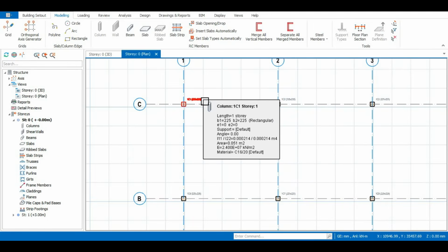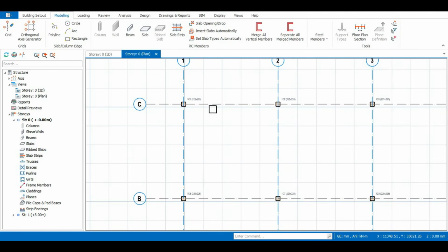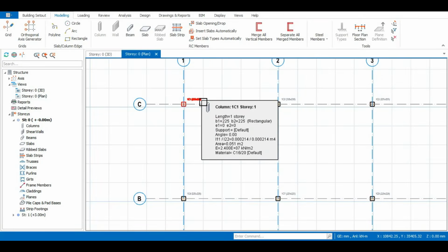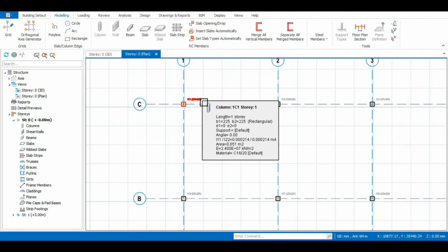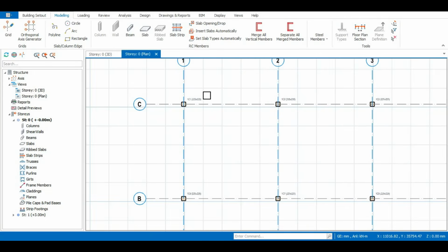And in this climate in Nigeria and most places in Nigeria, we usually have pad foundation being sufficient for our structures because we have some good gravel soil, and we have a lot of good soils that can withstand the load that you are putting on top of it. Basic structures like duplexes and bungalows, and sometimes even story buildings that are not too high. You can design pad foundation for that if the bearing capacity of the soil is very good.